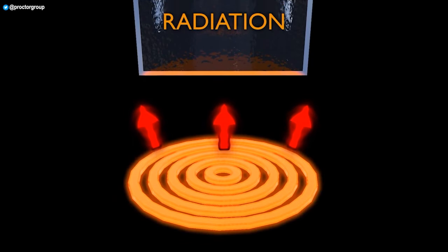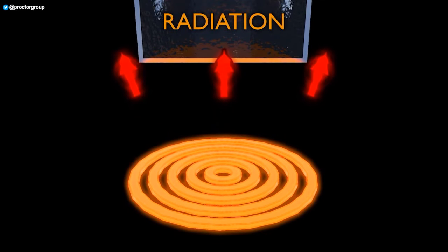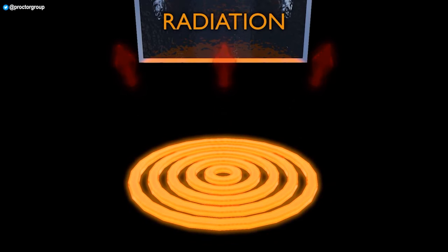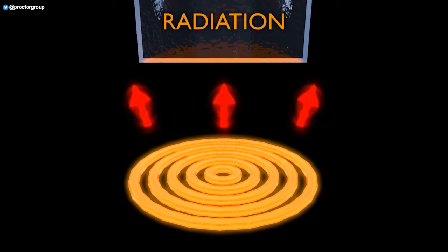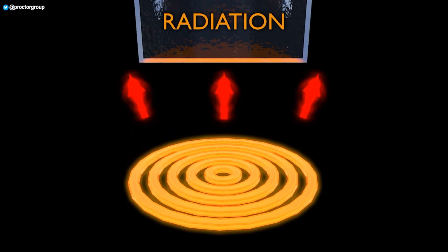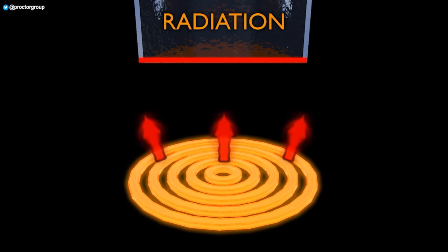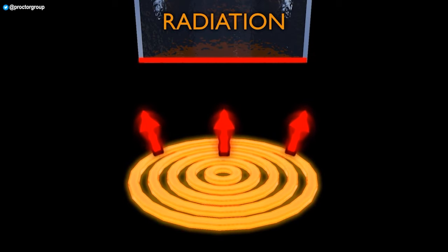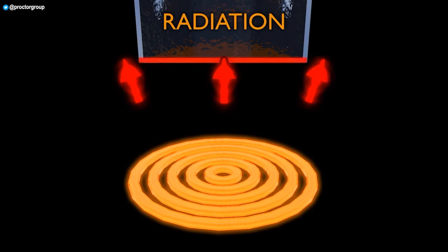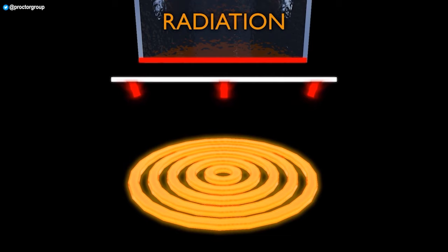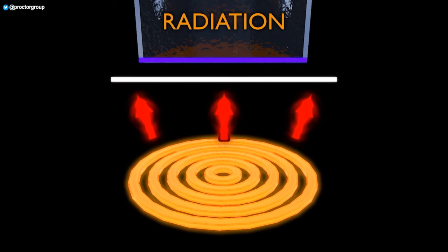Radiation. Radiation is the transfer of heat from one material to another, which occurs by means of electromagnetic waves. Radiation does not require either physical contact with the materials or a fluid medium. A warm surface such as our hot plate will emit infrared radiation, which can travel across a space, even in a vacuum. When these infrared waves strike another object, they are converted back to heat. The efficiency of this conversion process is governed by a property called surface emissivity. The lower this value, the less able a material is to absorb or emit heat via radiation. In construction, reflective foil membranes and foil-faced insulation materials can help limit heat transfer by radiation.